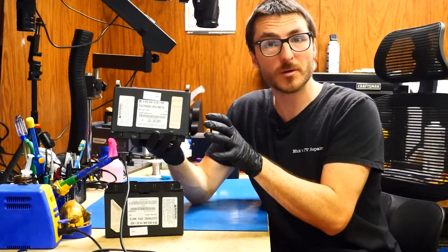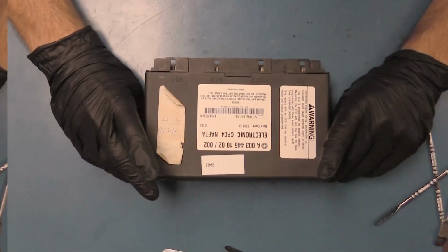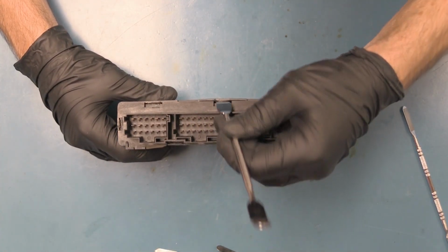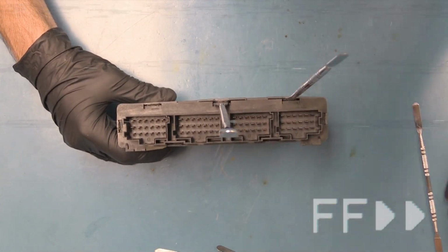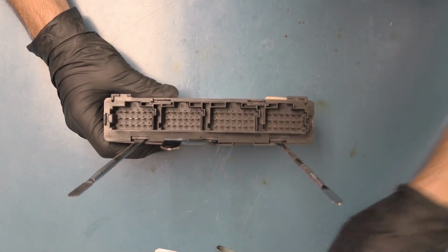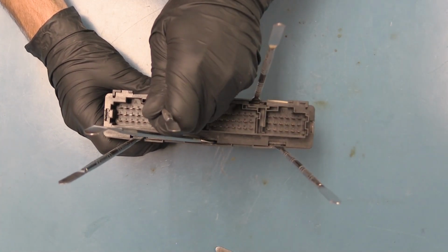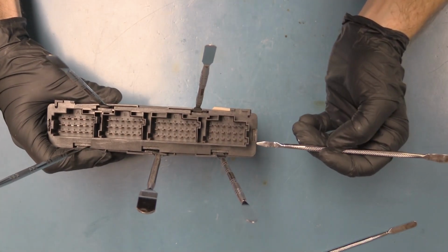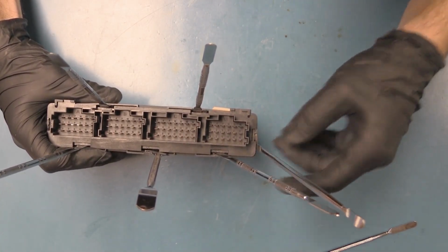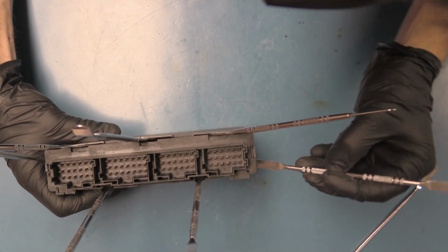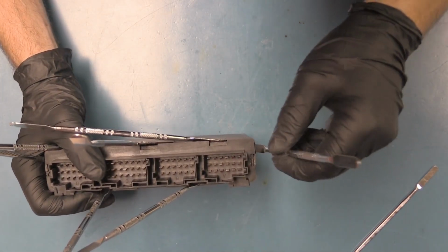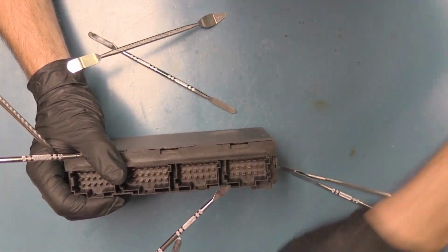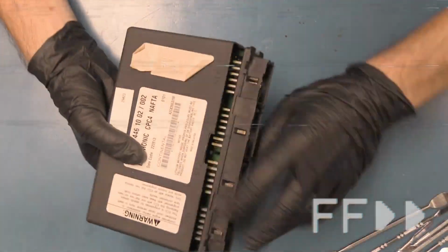I'm going to go ahead and open them up and show you an easy way to diagnose these. Okay, so we're going to go ahead and flip the CPC4 up, and I'm going to use these metal spudgers to pry the outer shell away from the circuit board here. Do 3 on that side and 2 on this one. And then I'm going to go on the side over here now. And then our final side over here. And there we go. Now the shell falls off.